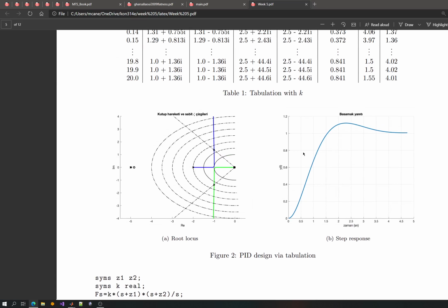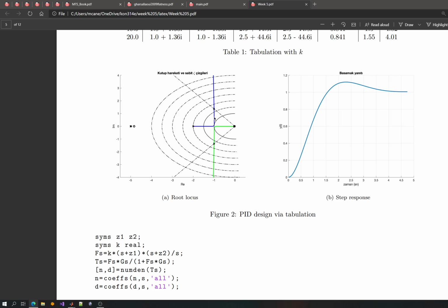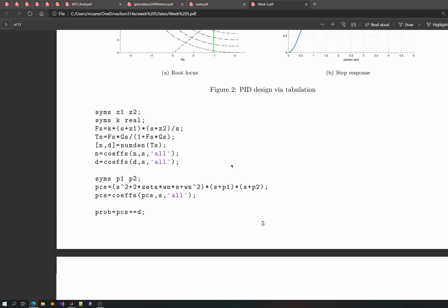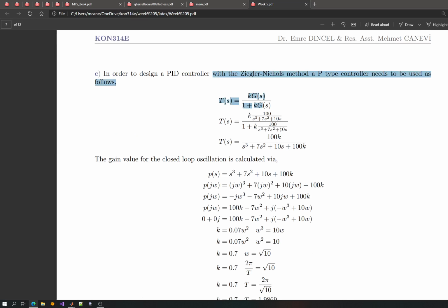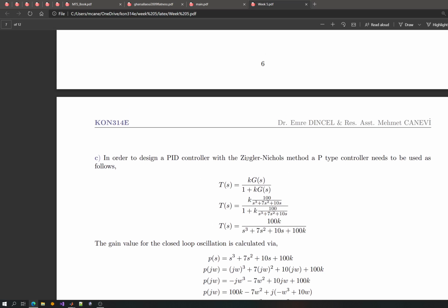And you can see some root locus plots that are accommodating these plots, since we can look at this in the root locus, so it will give us an idea of the dominant pole placement. You can see that the PID controller using the Ziegler-Nichols. Now, the thing with Ziegler-Nichols is it is very easy, but the only thing that you should do is you should have some parameters about the system and some basic parameters. One of them is the gain that is necessary to drive the system to marginal stability or to oscillation.